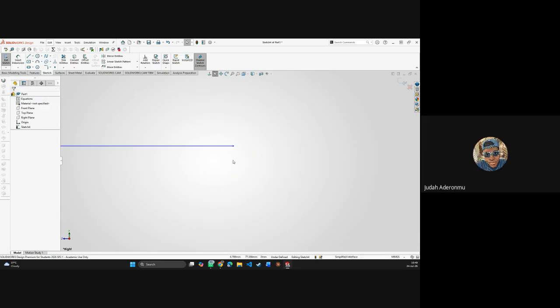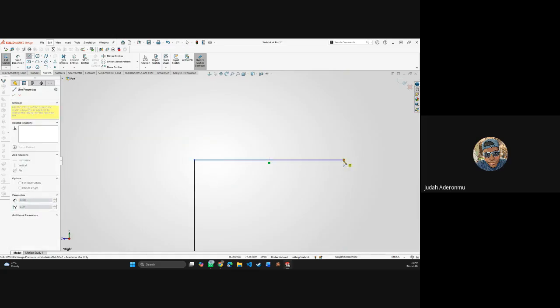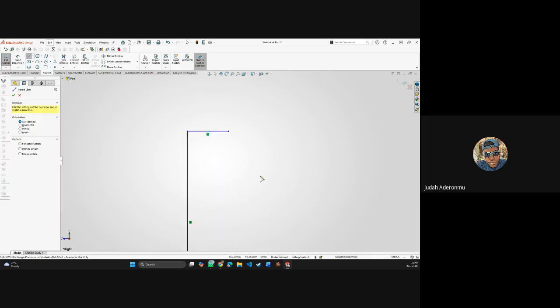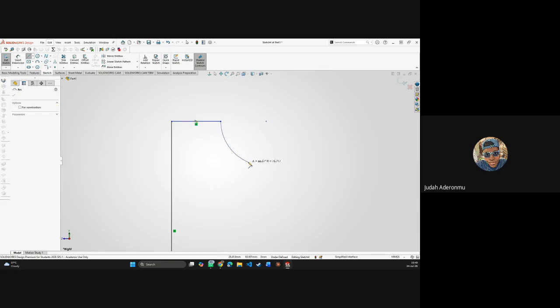Okay. So let me just go over it again. Let's say I have my line tool here. I draw a line. The minute I hover back on this line, it's going to come out as an arc. Once you hover on this point with your line tool and it turns orange, it's going to come out as an arc instead of a straight line again.